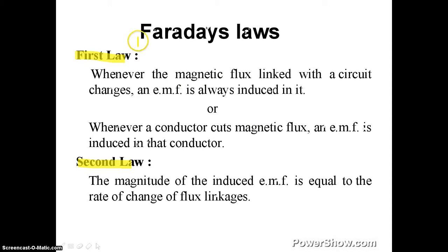Now what does Faraday's law state? Faraday's first law states that whenever the magnetic flux linked with a circuit changes, an EMF is always induced in it, or whenever a conductor cuts the magnetic flux, an EMF is induced in that conductor. The second law states that the magnitude of the induced EMF is equal to the rate of change of flux linkages.